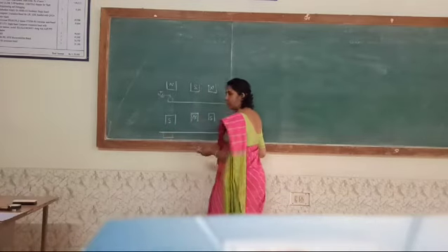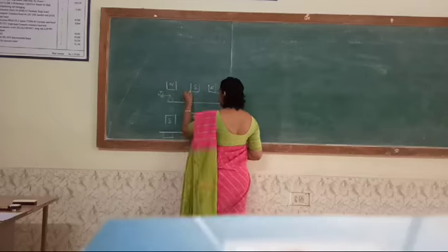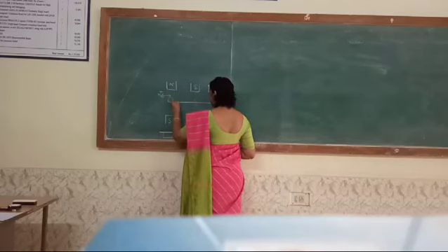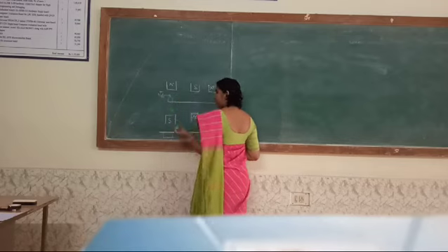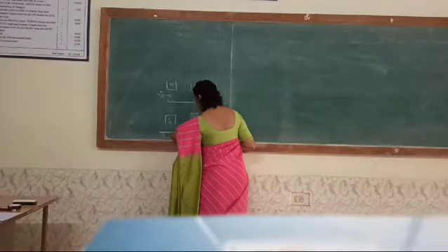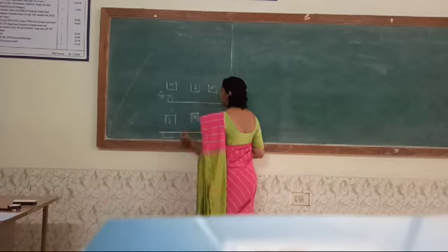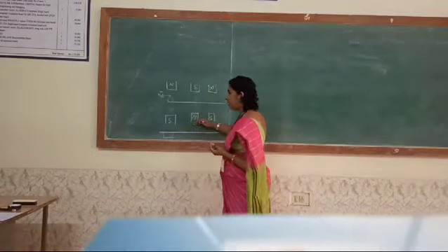There is a flux which is coming in this direction. Okay, and till this particular point, from here to here, once the conductor comes here, it is not under the influence of any pole pair. In that case, there will not be any flux. Then again, from north to south, which is from the bottom to